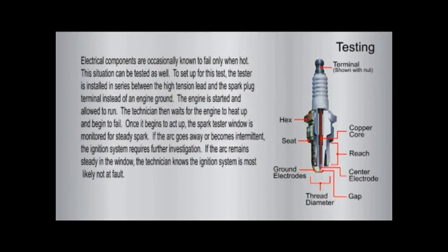Electrical components are occasionally known to fail only when hot. This situation can be tested as well. To set up for this test, the tester is installed in series between the high-tension lead and the spark plug terminal instead of an engine ground. The engine is started and allowed to run. The technician then waits for the engine to heat up and begin to fail.